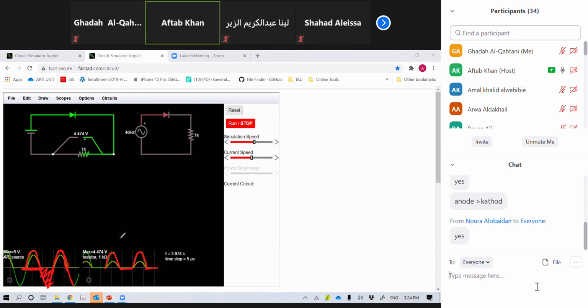So this is forward bias, this is reverse bias, this is forward bias, this is reverse bias. Getting the idea? Yes. So this is what we call a half wave rectifier circuit. That is, this circuit can rectify only half wave. Any positive cycle is here and we remove the negative cycle. Understand the point? So this is called a half wave rectifier. And what is a rectifier? A rectifier is basically a circuit which converts AC into pulsating DC.